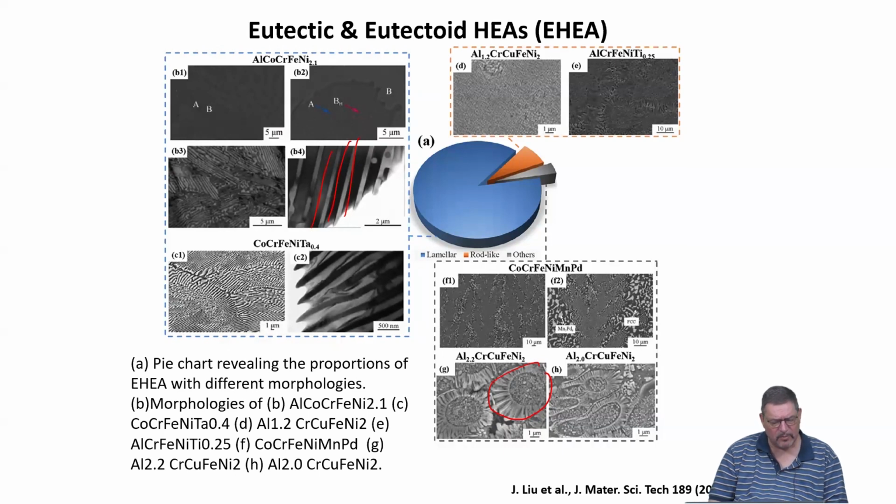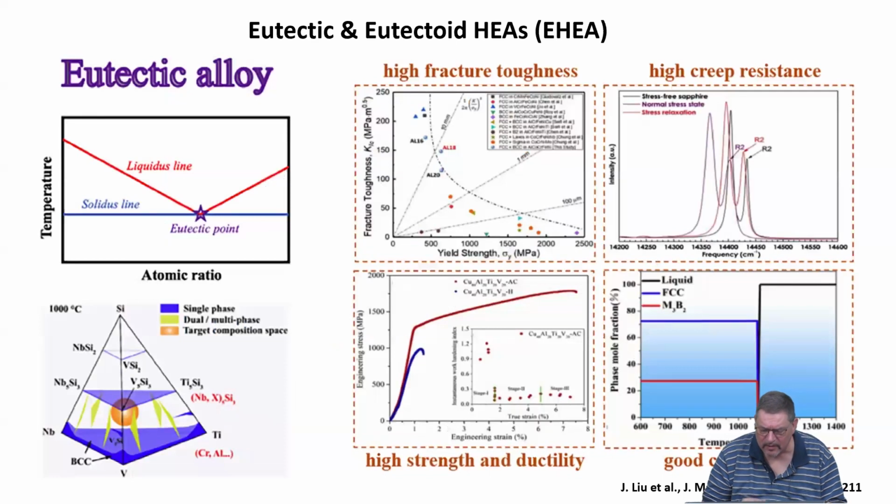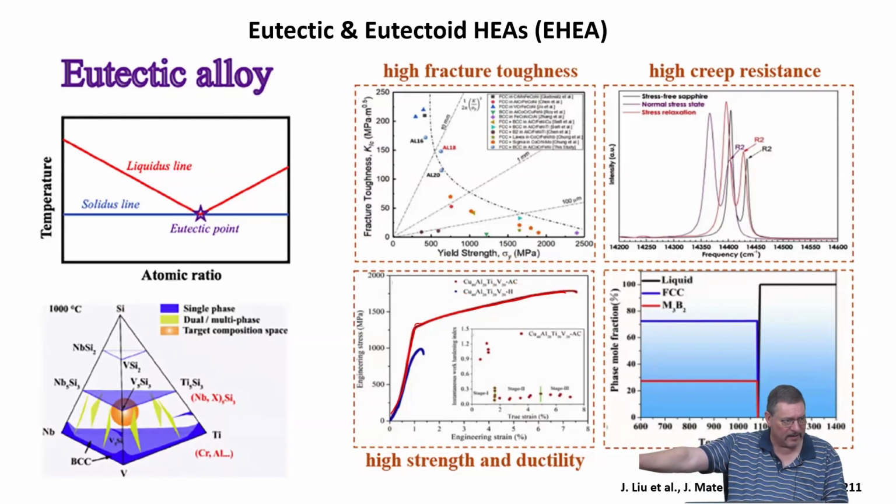Yeah, it is in terms of the mechanical properties, right? Because you see here that you get something like a very high strength, very long work hardening capability with high strength again and good ductility before failure or elongation before failure. And this is something which is really beneficial, because some of these materials are also, like you see here, copper, aluminum, titanium, vanadium, on the more low density side.